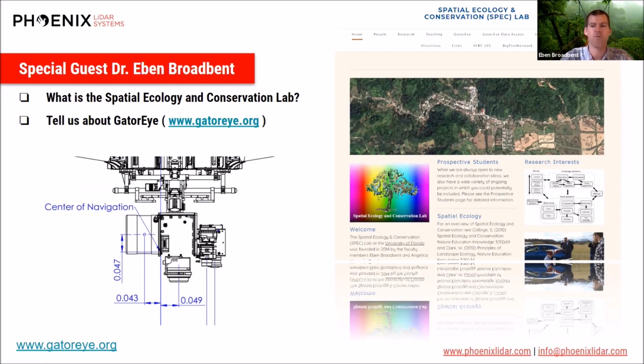I've been talking to and working with people who are experts on thermal camera systems, and in fact just recently down in Costa Rica, and they were really saying how they've been suffering so many complaints during conferences and trying to publish their papers about this vignetting of the lens that happens. And basically what happens is that if you don't have this really excellent custom designed external components, then as the system is moving through the air and as it interacts with the environment, it heats at different levels. And the non-equal heating of all those components results in issues with the actual thermal imagery data.